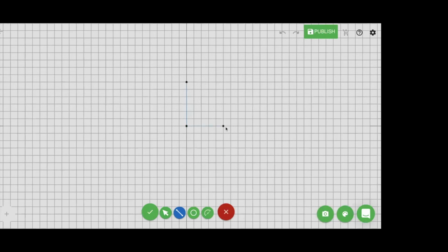And when I make vertical lines and horizontal lines, they'll kind of automatically follow these grids for now, but you can also drag them and change them later, but it kind of helps guide you. So I just made a full L shape and kind of closed it, and you notice that it went from dark blue to light blue, and that meant that the actual sketch closed the loop.